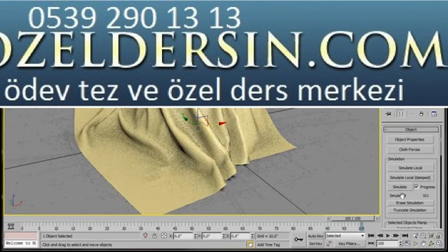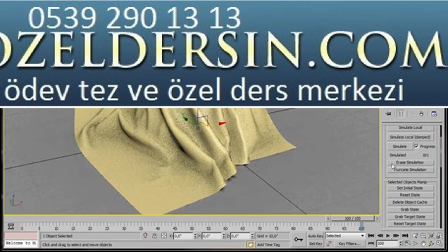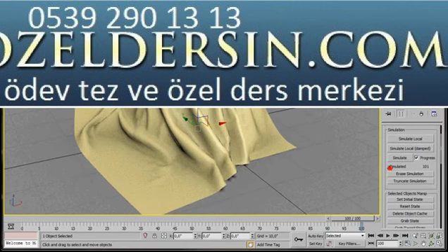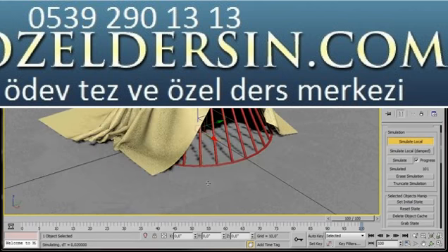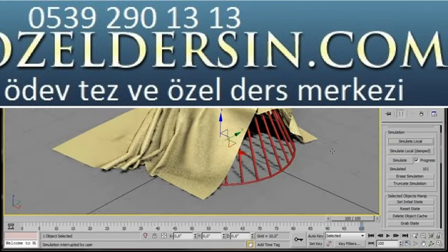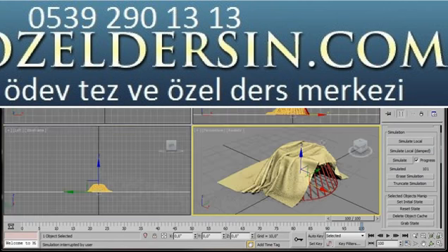We'll just come back over here and click on Erase Simulation. And then scroll down a bit further and click on Reset State. And you can redo it. I'm going to scroll up now and turn on Simulate Local. This will just relax and soften the mesh a little more. I'll leave this on for a few minutes. Okay, a few minutes have gone by. I'm going to turn off the Simulate Local now.